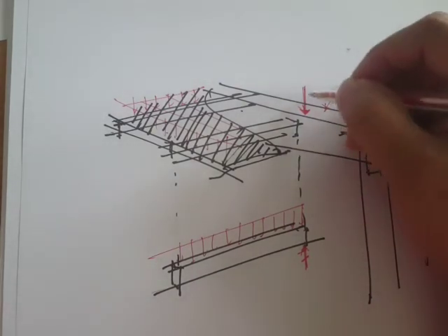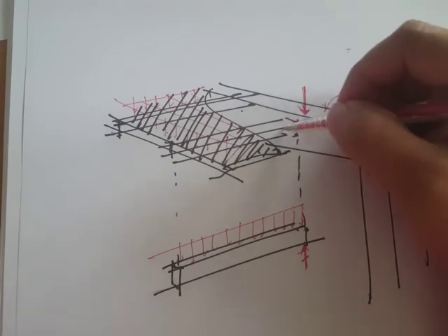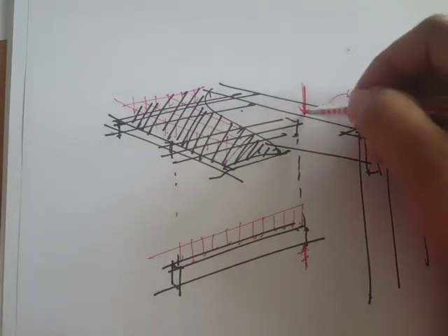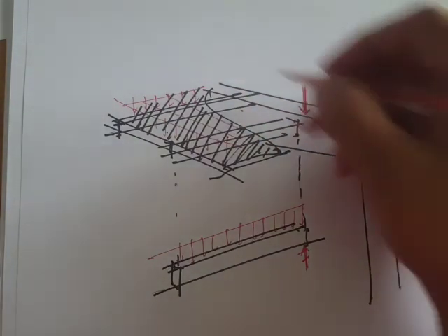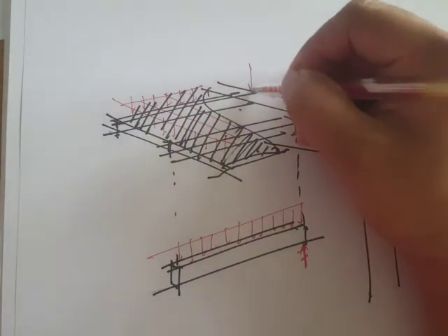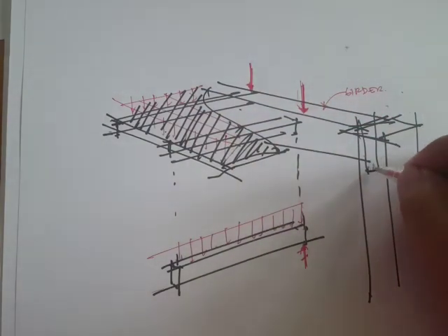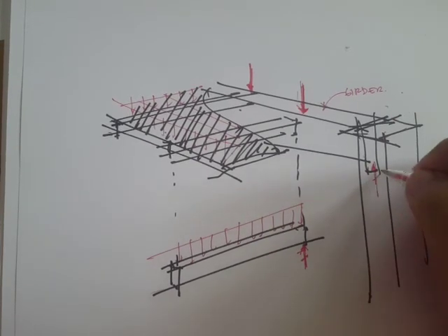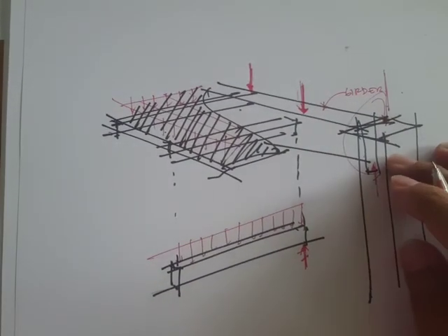Okay, it's not absolute, because what if the spacing of the beams is narrow, we'll try to check if that's going to be a line load distribution. And then of course, if you analyze this girder, you'll get a support reaction from the columns, and the support reaction will be the concentrated loads to the columns.